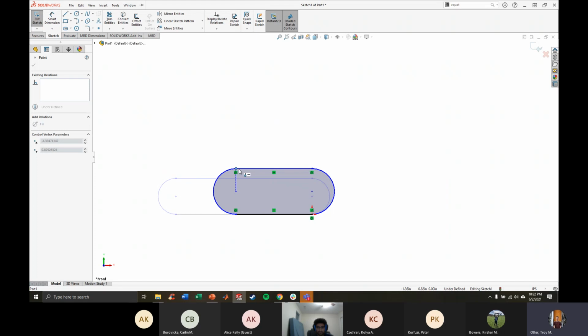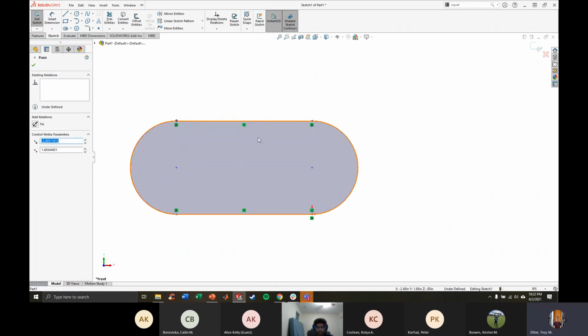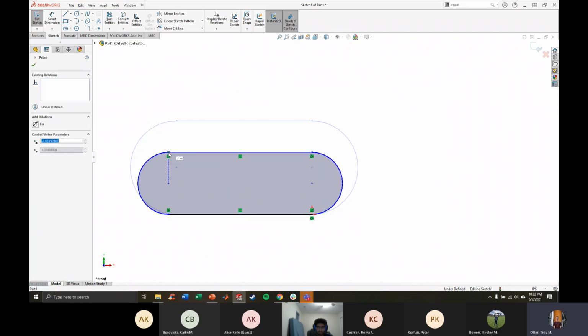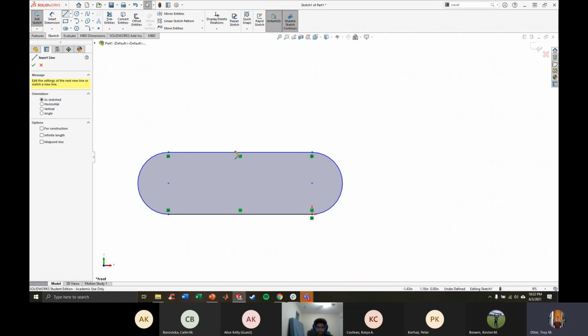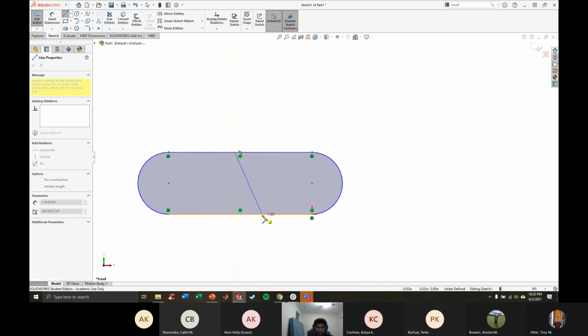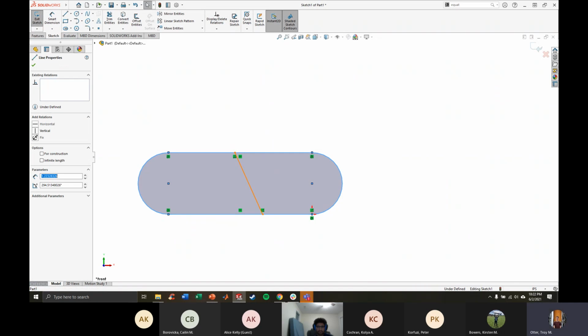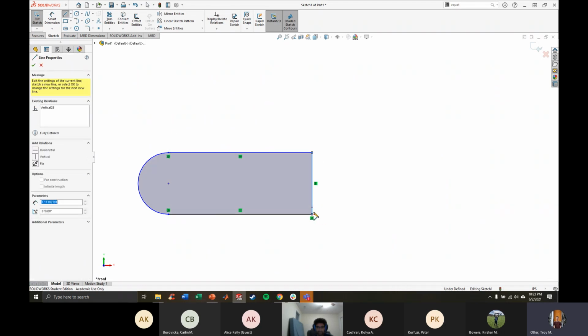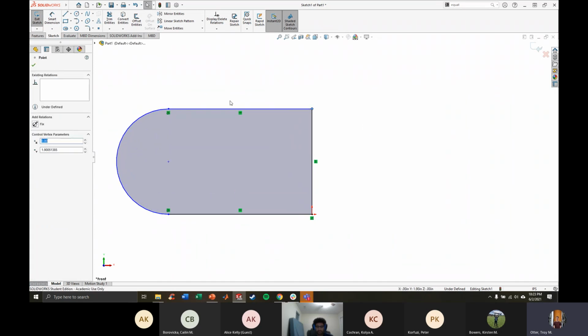So a couple other things to note. When you have a closed section like this, it'll shade on the inside. So when we go to pull out or extrude this sketch, there needs to be a closed surface for the most part. If I were to say, what's going to break this? This is better than Creo. Yeah, so if I were to just remove this, then it's an open sketch. There's nothing that I'm going to extrude from here. I need to close it somehow.